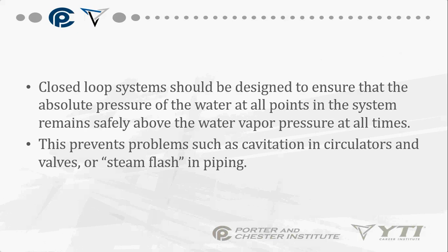We didn't have water-based boilers. So that component was invented simply to prevent cold water from entering that hot boiler. Sorry, we were talking about steam ones yesterday. That's why it was on my mind. Yeah, that's why you have the Hartford loop. Yep, which was invented in Hartford, Connecticut, by the way.